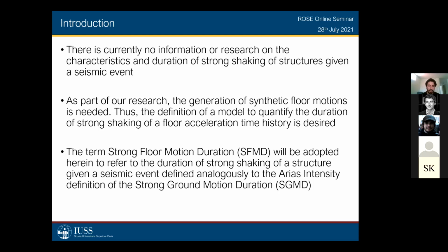So when you generate synthetic ground motions, usually you use the strong ground motion duration. That is a very well-defined parameter because it has been extensively researched by seismologists. But in the case of floor motion, we don't have this kind of information. So this is what this investigation focuses on.